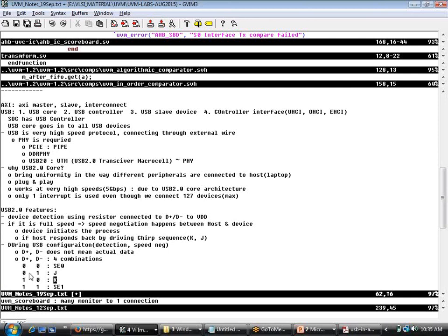During normal operation, 0 1 and 1 0 don't make sense, because they are conflicting, right? During normal operation, you either send 0 0 on both D plus and D minus, or 1 1 on both. Only because we are not doing normal data transfer, but some kind of speed negotiation, and it can be done using other aspects also, suspend, resume.